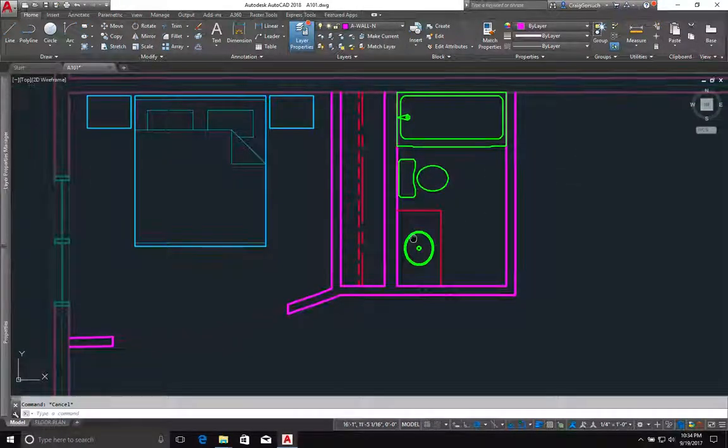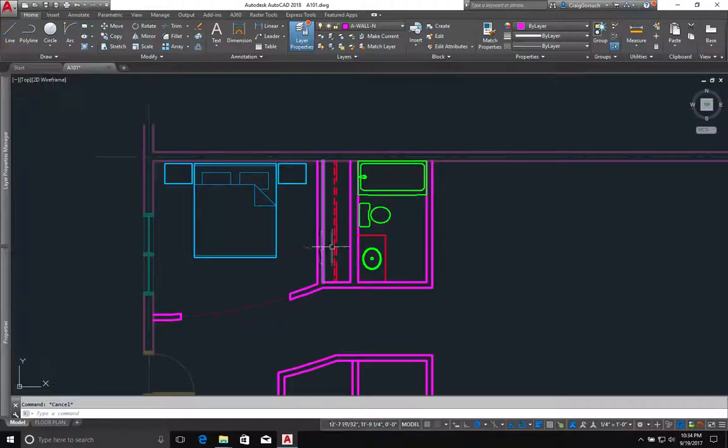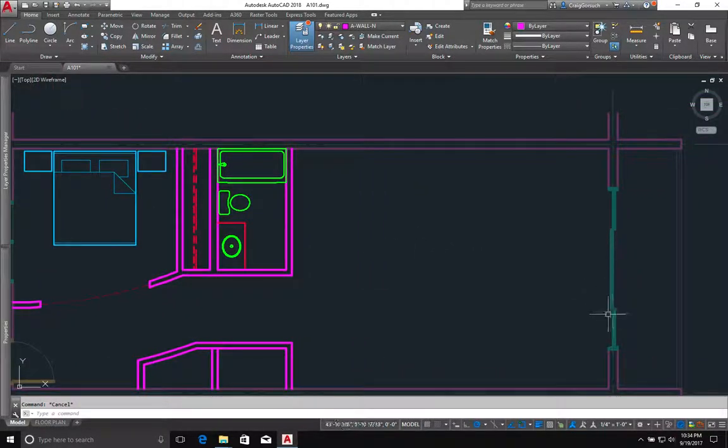Well, I need to put some doors in here, and I'm going to start with this section here. I want some sliding doors, because I already have some sliding doors over here. You'll notice a couple of things. Number one, they're on the glazing layer, which means these are glass doors. Obviously not solid Herculite glass doors, but your typical indoor-outdoor sliding glass doors that you see in any apartment or a condo. And also the layer's locked.